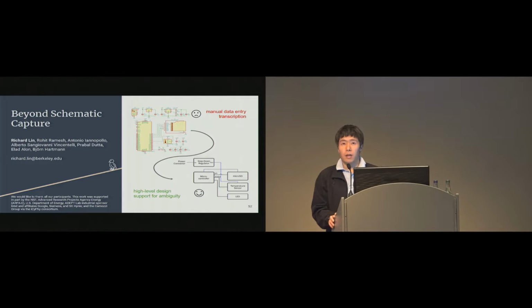I see. So let me think about this for a moment. I think our idea here, the goal at least, is to have a sufficient electronics model where in most cases you would not be able to mess up, right? Like it would model things like absolute maximum voltages, maximum currents, which are probably the most common issues. Now, of course, there are higher level issues like RF interference or possibly even thermals or high frequency issues. Those are hard problems. Maybe the solution is we'll incrementally play whack-a-mole with those as people encounter those issues and extend our models. But yeah, debugging is hard.